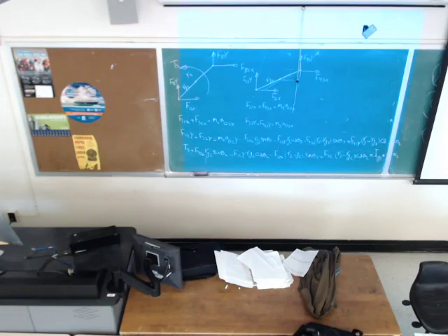Summation of forces: I have these 2 forces in X direction, F14x plus F34x, equal to the mass of link 4, M4, times the acceleration of the center of gravity of link 4 in X direction. F14y plus F34y equals M4 times the acceleration of the center of gravity of link 4 in Y direction.